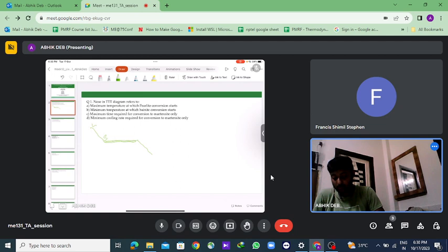In some books they say only the pattern will take care of the solid shrinkage, and in some other places they say it will include both the solid and the liquid shrinkage, the latent heat part and the solid shrinkage.